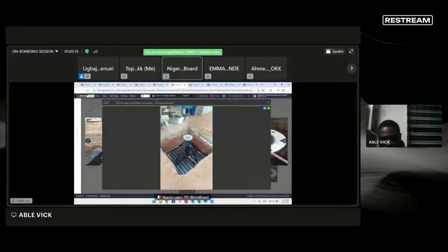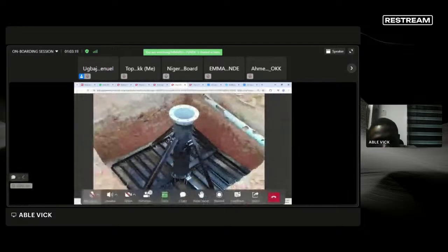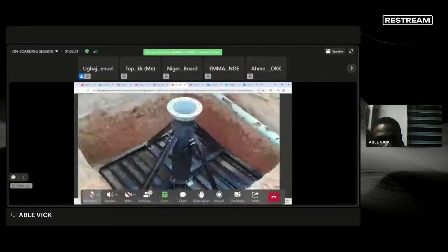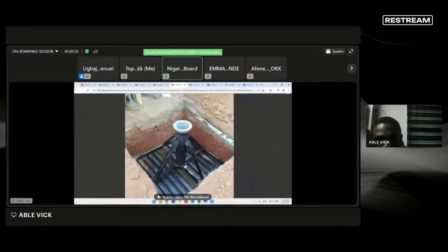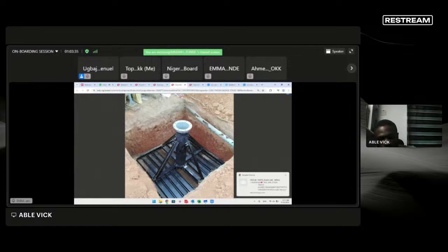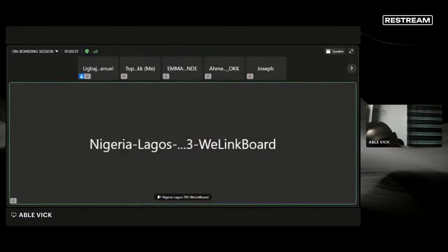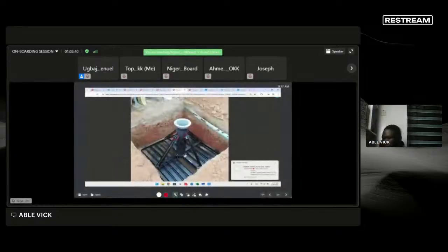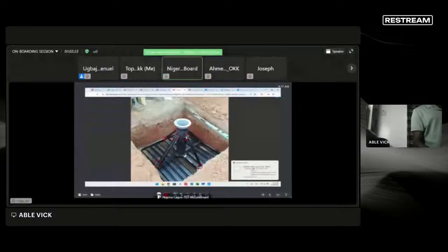So this is how the foundation is going to look like. You can take a photo of it. When they're installing, the objective is to install and have something like this. You understand it? Check all your diagonal braces here. All your diagonal braces have the lock nut all around. So if this is not done like this, GSC is not going to pass your QC.